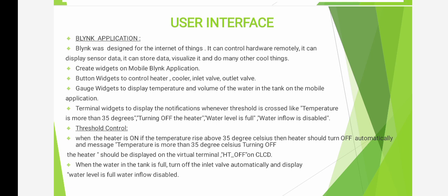Gauge widgets to display temperature and volume of the water in the tank on the mobile application. Terminal widgets to display the notifications whenever a threshold is crossed, like temperature is more than 35 degrees, turning off the heater, water level is full, water inflow is disabled.